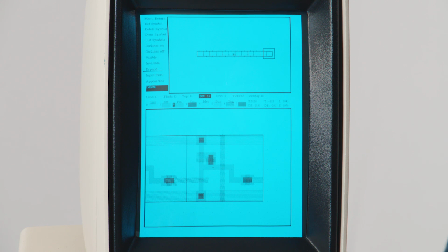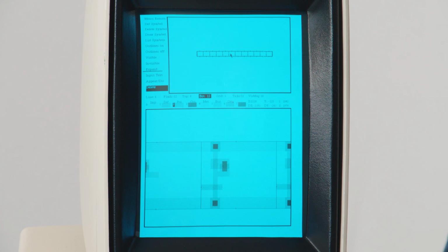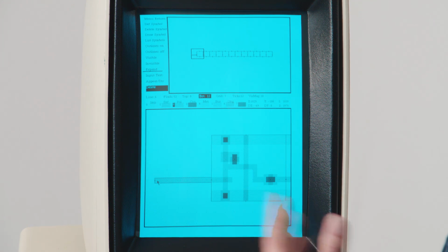And so again, I can go back to this upper window if I want to verify that they're all correct, or that things are connecting properly. I can say, show me the one in the middle, and it'll show that to me below, or show me this left-hand edge, because I want to know where to connect down here. So I might skip to that left-hand edge. I could then take this connection point and start drawing additional circuitry outside of this cell to connect it to the rest of the chip.